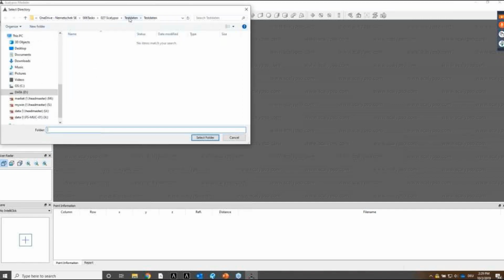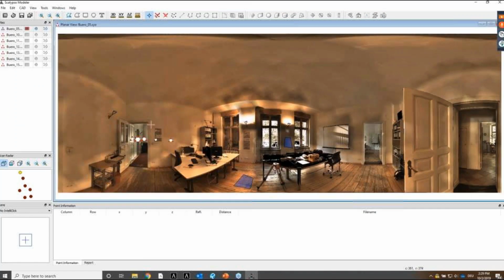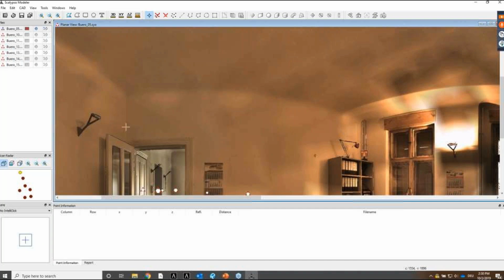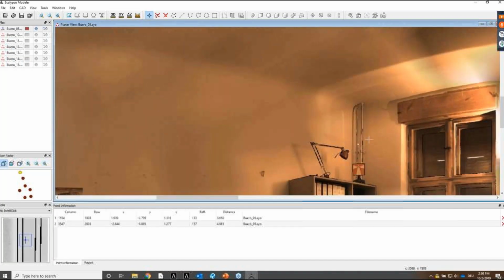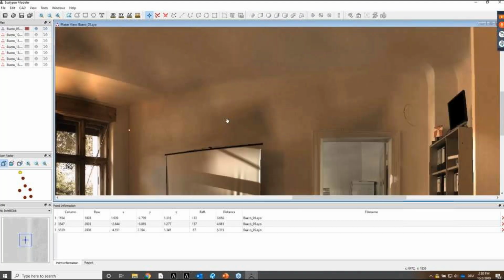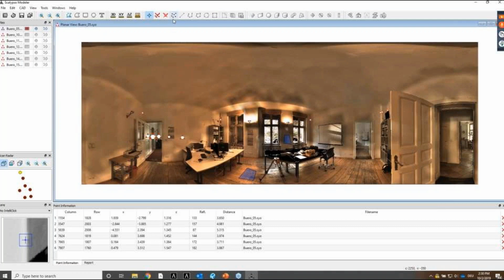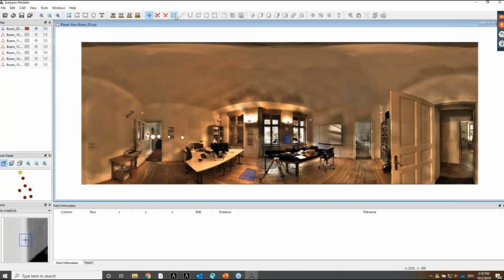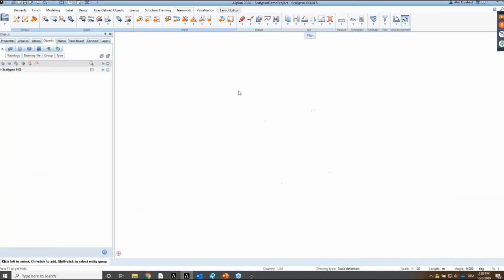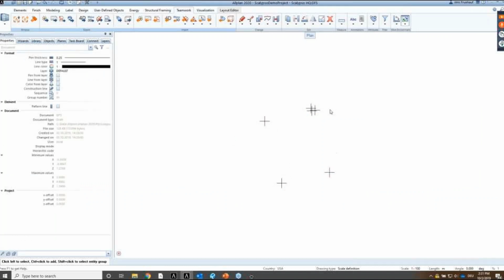But what you can do now is import the data you get from an elevation. So this is a 360 picture that also contains some metadata regarding the points. It's the result of a laser scanning. It's a laser scanner that measures clouds of points. And what you do now, you just select some reference points of interest on the picture, because the picture has the metadata behind it that knows exactly the dimensions. So all you have to do is click on the pictures what points are relevant for you to be able to draw this room, and then you can import these pictures into Allplan.